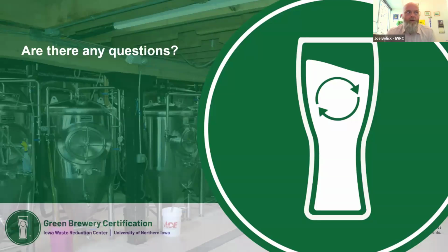A couple of his fermenters are slightly larger than they probably need to be for the rest of his system, and they're rated up to a high enough pressure that he actually just runs a line from the top of that fermenter and uses the CO2 generated from the fermentation to supply his tap handles, so he doesn't have to hook up the bulk CO2 or the canistered CO2 to his tap lines.